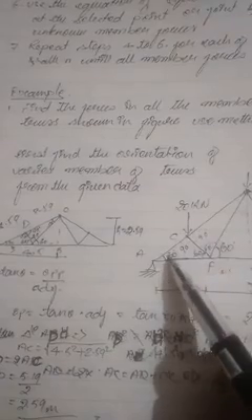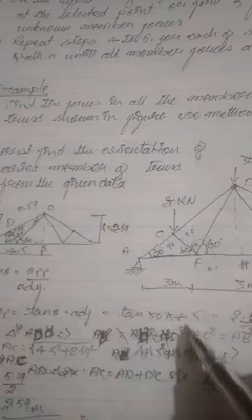This distance will be found out by, see here, tan theta is equal to opposite by adjacent. So the opposite, DH, is equal to tan theta into adjacent. Tan theta, here it is 30 degrees, because I am taking this complete triangle. So this is tan 30. The adjacent distance from A to H is 4.5 meters. So opposite distance DH, if you calculate this, you will get 2.59 meters. From here to here it is 2.59 meters.